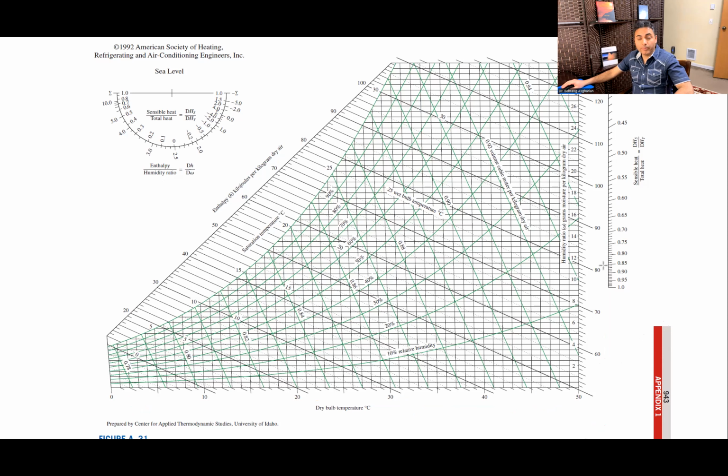The first thing you need to know about omega in the SI version of the psychrometric chart is that the humidity ratio is shown in grams of moisture per kilogram of dry air. This part is very important. It means this unit is not exactly the basic SI unit if you want to use it in equations, because what we have in our equations as omega is kilograms of moisture per kilogram of dry air. So what do you need to do? We're going to show that in our equations. When you read these values, for example you see a 6, you have to divide the actual value of omega by 1,000. So this is 6,000ths, basically. Or this value of omega that is 10 here, that is 10,000ths.